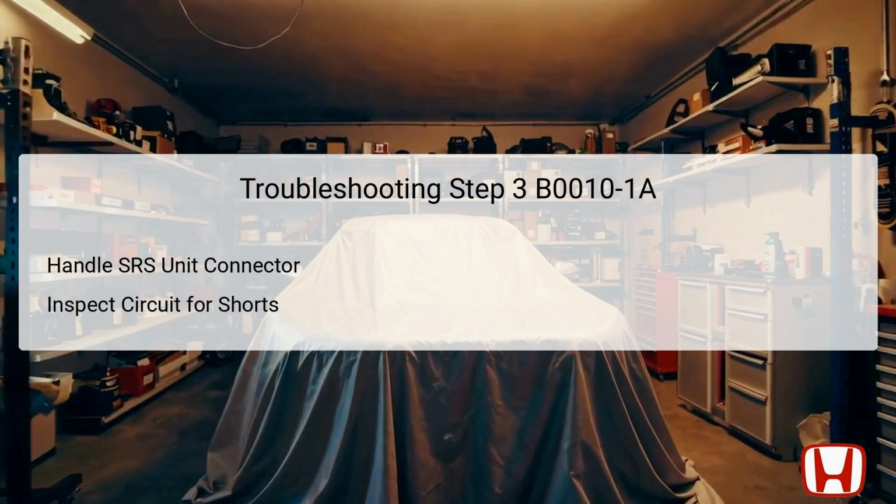The objective here is to perform a shorted wire inspection by verifying that there are no shorts present in the wiring, which must show more than 1 megaohm of resistance. The technician can ascertain whether the wiring system is intact or if there are malfunctions preventing proper electrical flow. If any abnormal readings are detected, this signals an issue in the circuit that must be addressed.